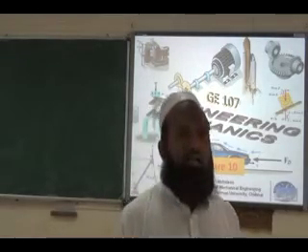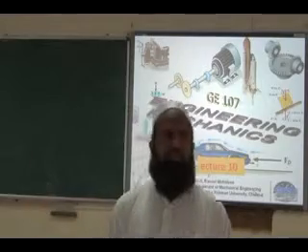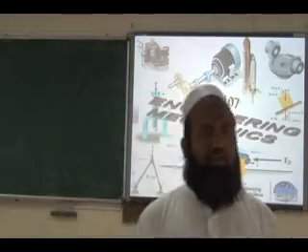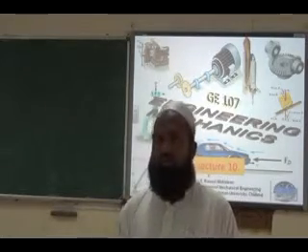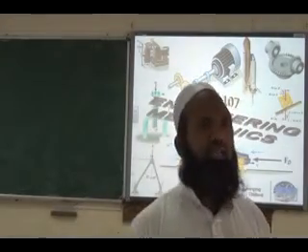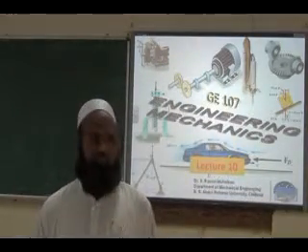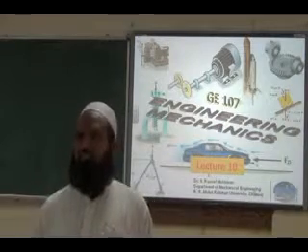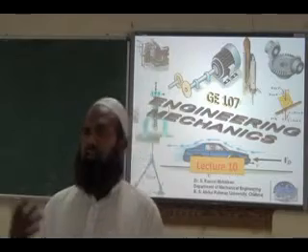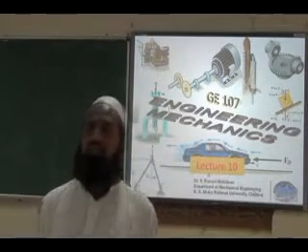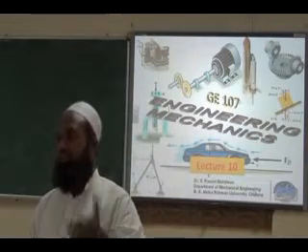Considering the equilibrium condition and also the other law, every action has an opposite reaction. The third law, we have solved problems of support reactions. Generally we have considered beams and many components which have support reactions. Wherever you are constrained or restricted to move, you will develop a reaction. You will show your resistance. That resistance is called reaction. The reaction may be of any kind according to the degrees of freedom you have. If you have 3 degrees of freedom, you will have 3 reactions.